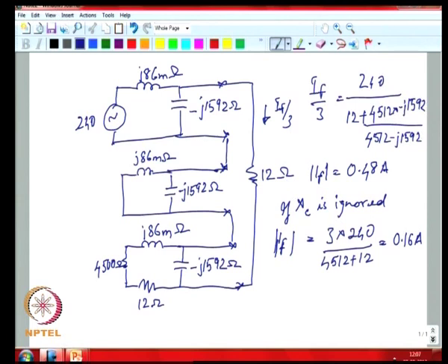If you neglect the parasitic capacitance, you would expect a smaller current, but because of the parasitic capacitance, the actual current would typically be higher, especially when you have high resistance grounding. So, that is when your unbalance really shows up as unbalanced currents flowing through your parasitic capacitors. So, some of these levels can actually be used to set how sensitive your ground fault trip devices, ground fault current interrupting devices, need to be set.